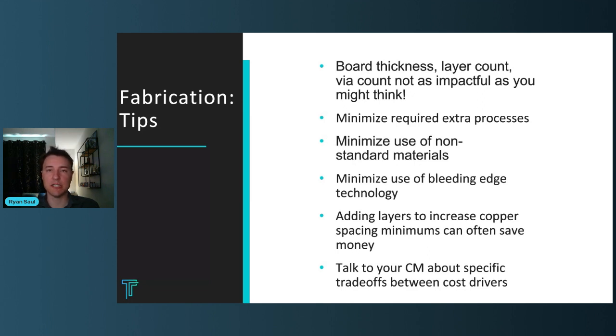Just let your fabricator take care of it. Have them send you an as-built stack-up for approval so that you're comfortable with what they're about to do. You can even recheck their math if you want. But you're going to save a bunch of money that way, I guarantee it.